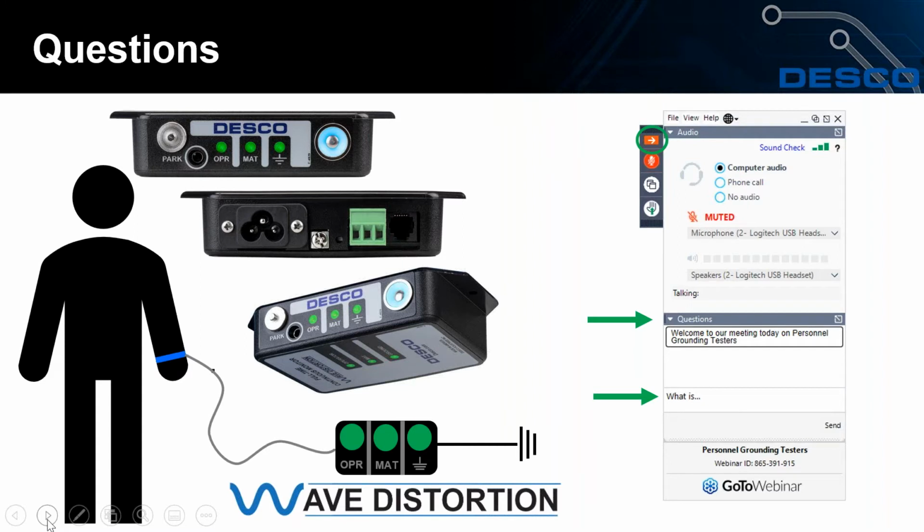The standard does allow you to write a tailoring statement into your ESD plan for the use of continuous monitors. As I mentioned before, you're allowed to eliminate the written test log if you were to use a monitor. So you would just write into your plan that that's what you do for wrist strap testing. Another question, Jeffrey?